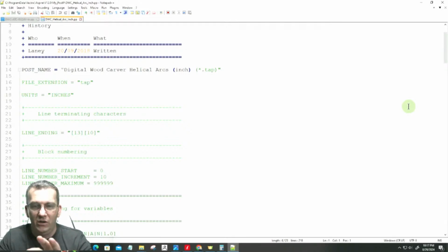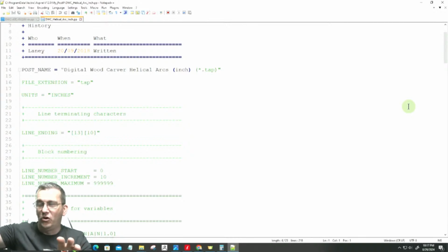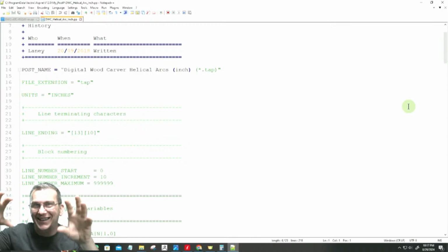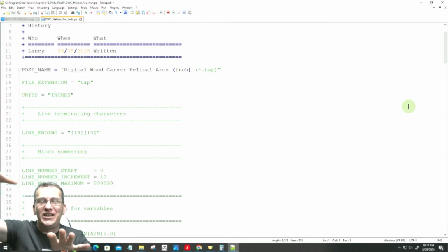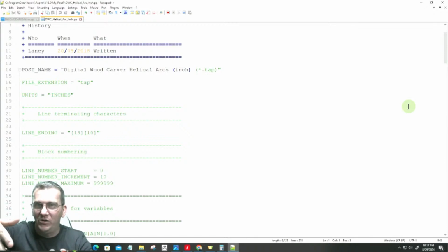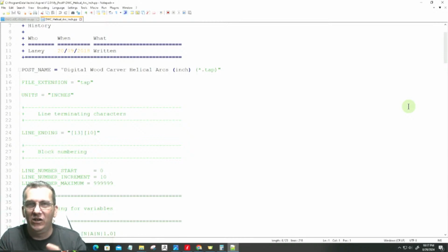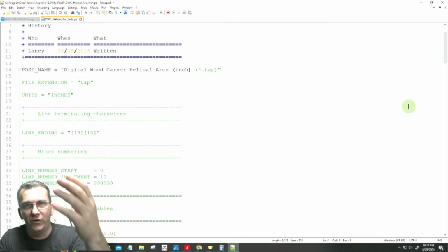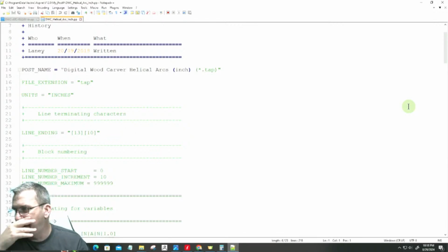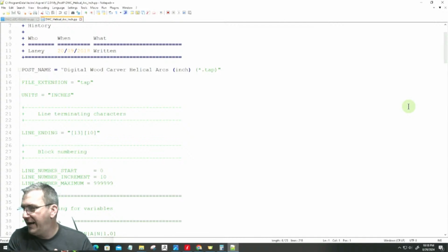and your rotary axis is programmed to your control board to be A, not Y or X or whatever, it's plugged into the A port and the A driver on the brain, right? Then you need your G code to spit out A values, right? So it has to turn one of those values into that A. Otherwise, it's not going to move properly. So just make sure that you're using the correct post processor for your machine, for your controller, and all that stuff.